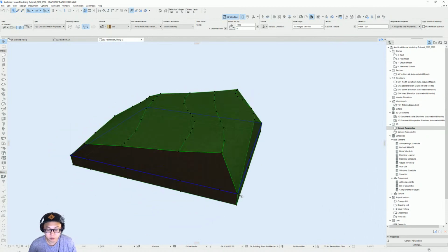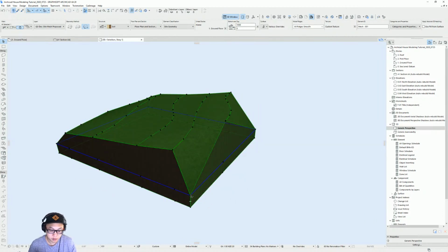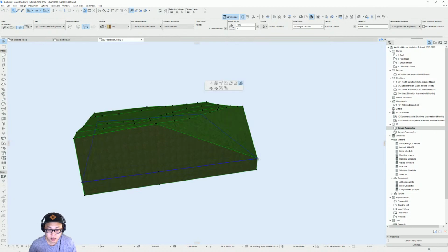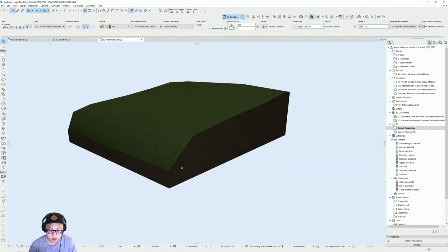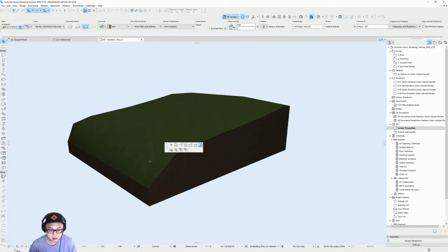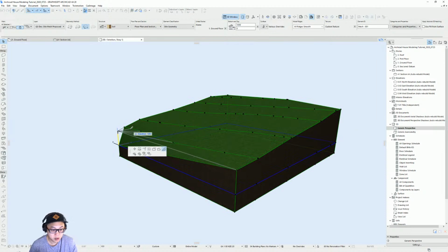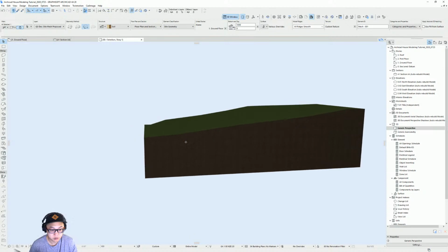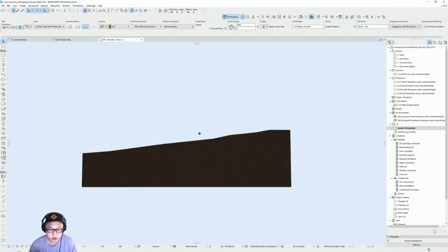Okay, now you see some of the corner of the mesh didn't move. So you can just move them individually if you wanted to, like in 3D. You mouse over the point and you change the Z. You can type in the value. I'm just going to type in 3000. And this one, I'm going to type 3.5. And this one as well, roughly. Oh, you don't even need to type. 3. Or you can just reference this. Yeah. Okay, so now we get a mesh.